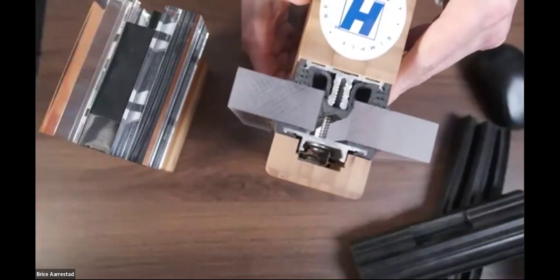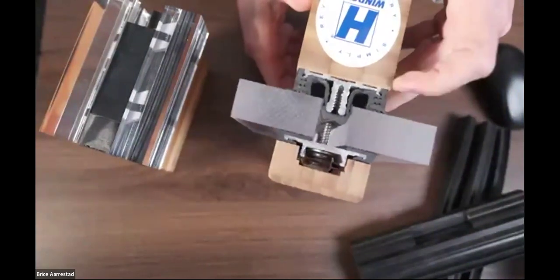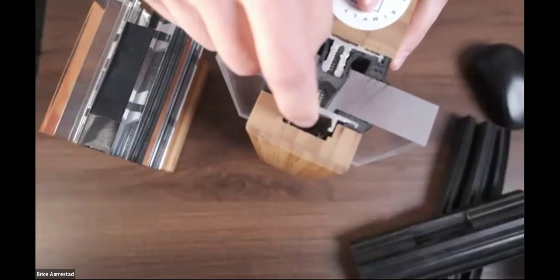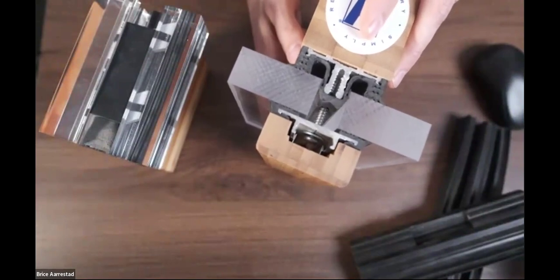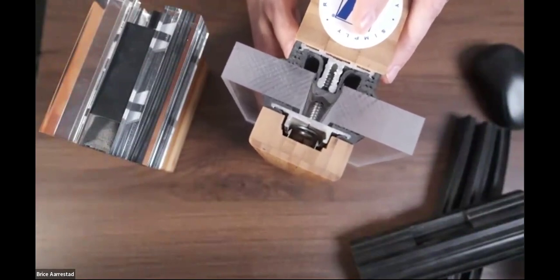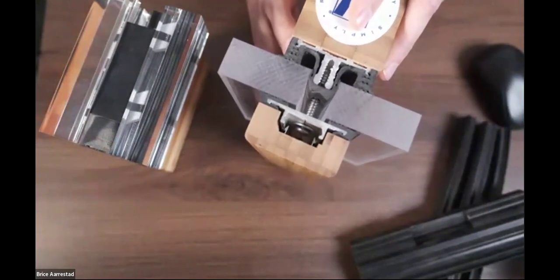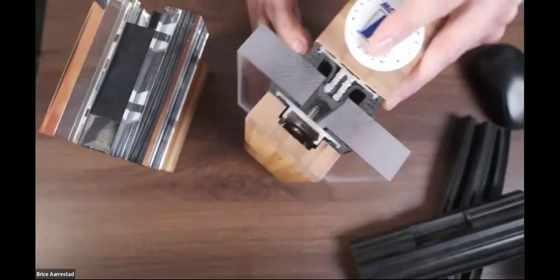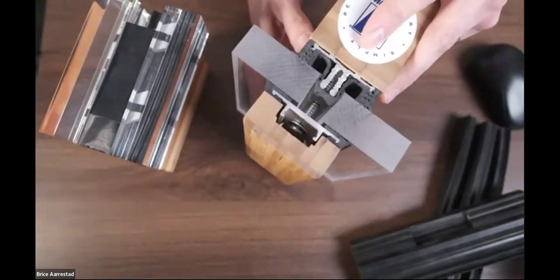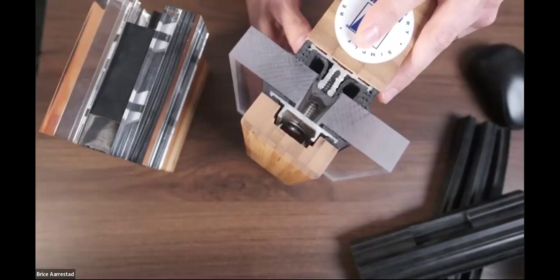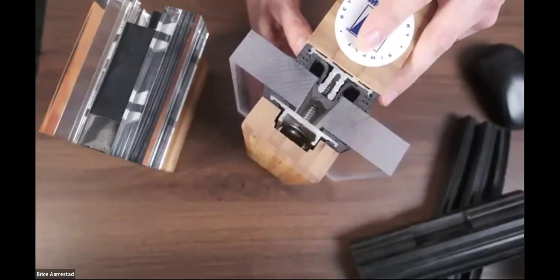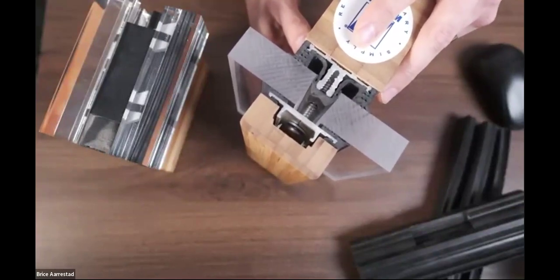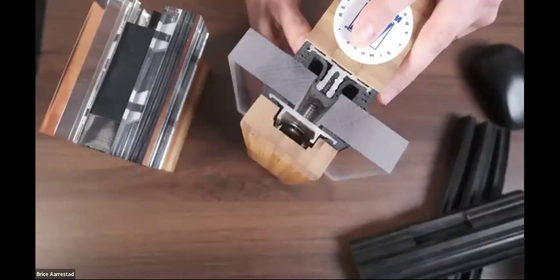And if you look down the end of it, you're seeing the aluminum cap, pressure profile, and then there's a clip system. So the wood member is screwed to the clip and the clip is snapped onto the pressure profile. So when you need to maintain this, refinish it, or paint it, you don't have to dismantle the entire system. You just pull off the snap cover and can refinish it. The gaskets stay in place, the glass stays in place. So it's a really easy to maintain system.